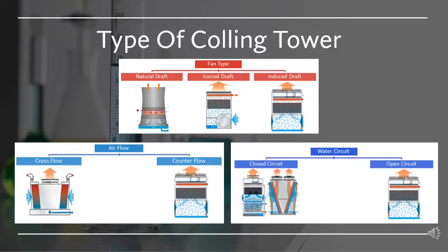In a forced draft cooling tower, the fan is usually located toward the base of the cooling tower and forces the airstream into the cooling tower. Natural draft cooling towers do not use a fan. Natural airflow is produced by the density differential between heated and cool air.